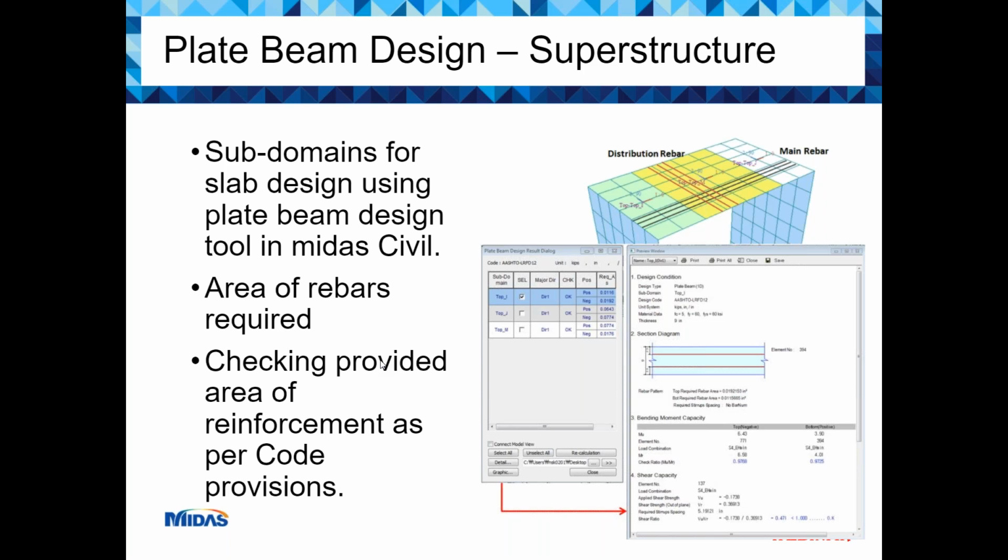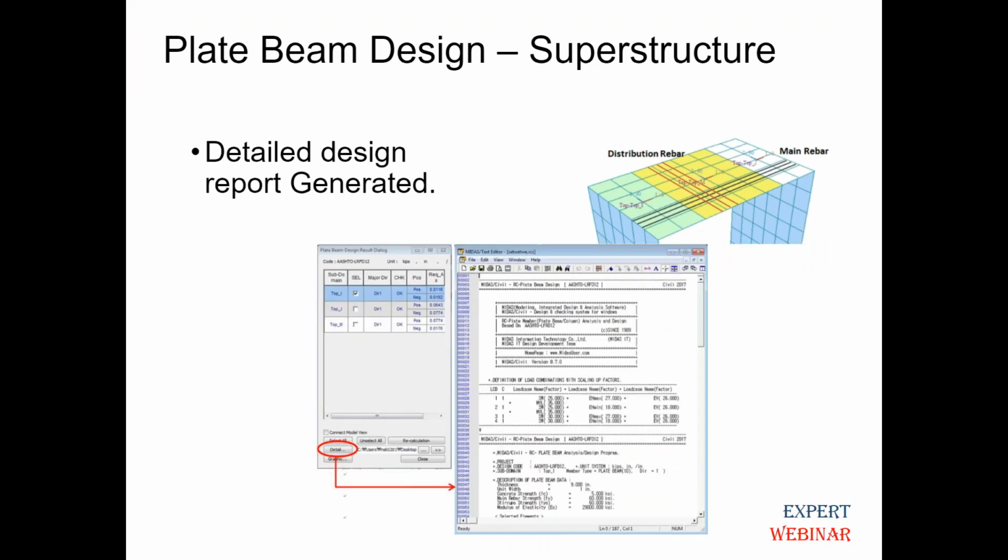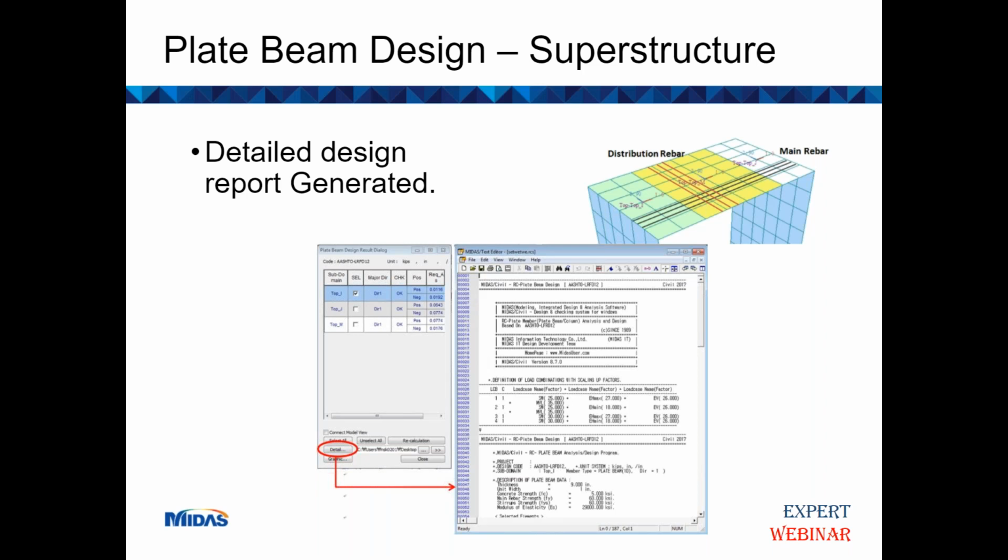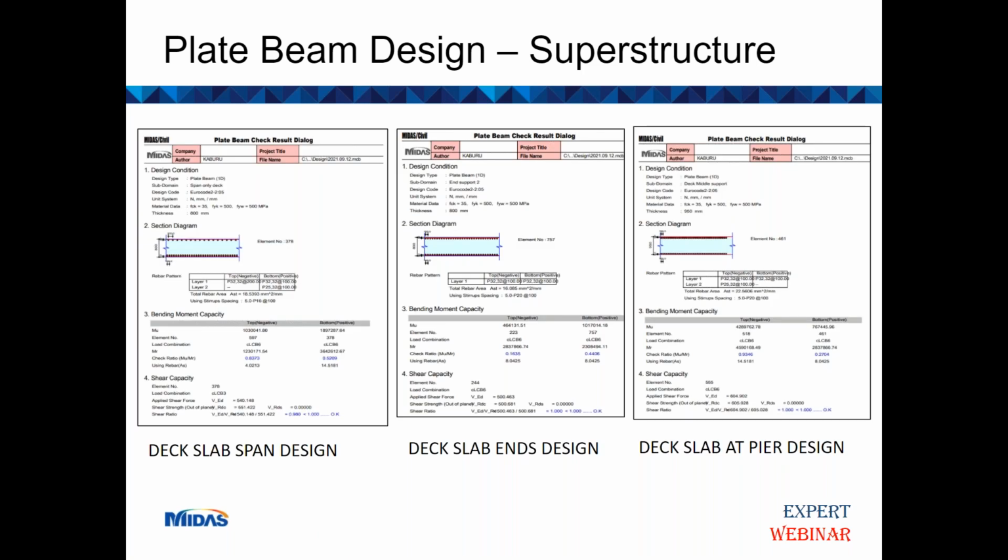and you can easily get to understand what is happening when you're using Midas. You realize these are some of the results in the design, and you can see the output is really easy to understand. You can see that this is the element that has been selected by the software, and the element has maybe this type of bars. These are the bending moments that have been considered, and of course the utilization ratio, which is very important to you, because you don't want a utilization ratio that is very low or over and above what is acceptable.